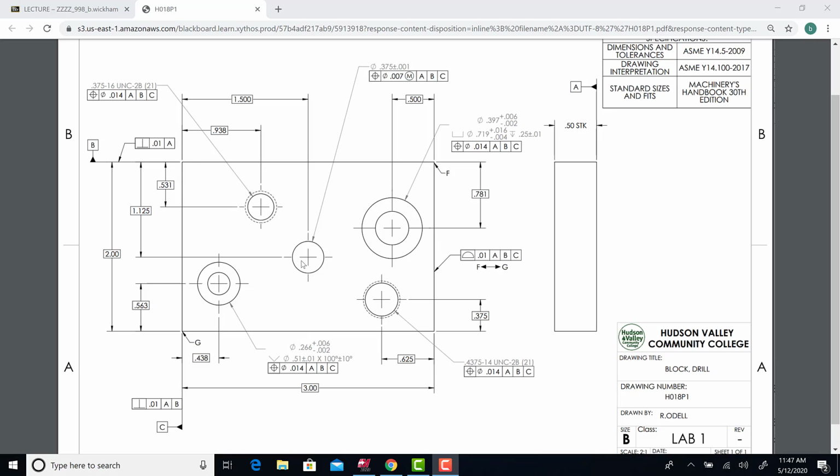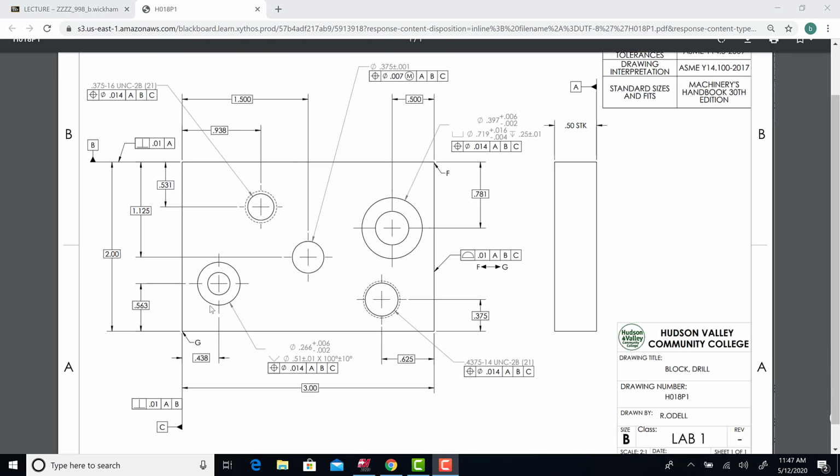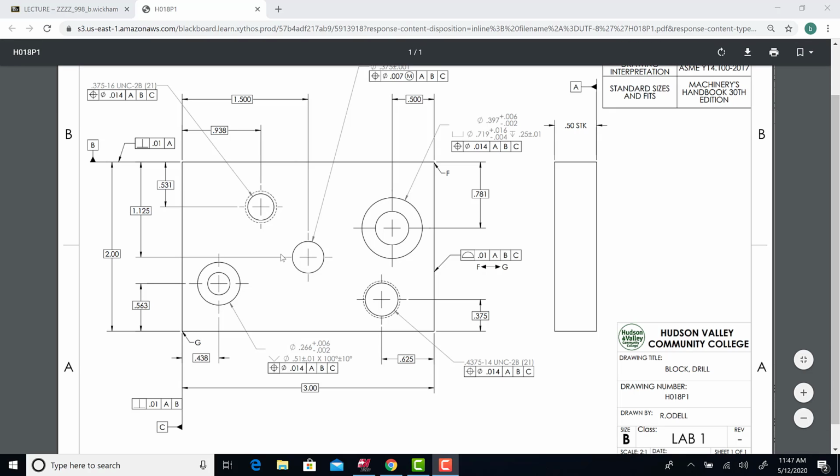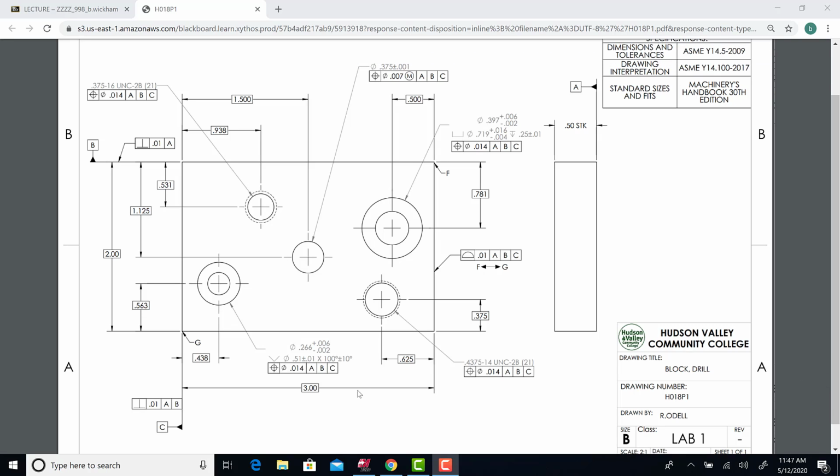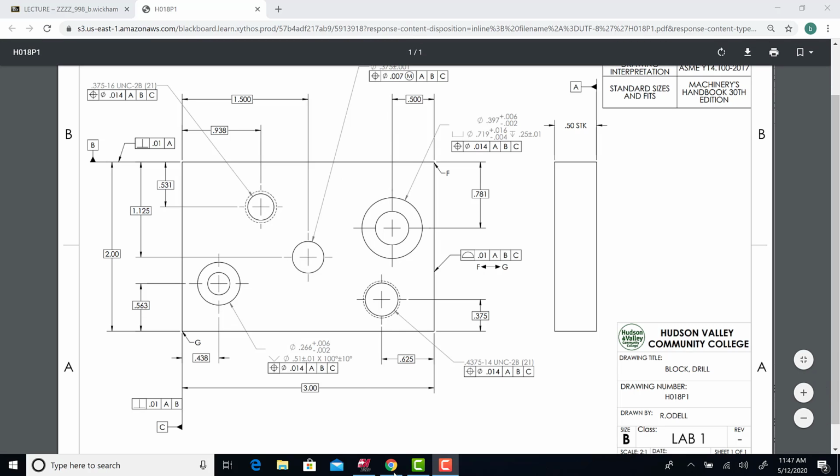The 0, 0 for this feature is the upper left. What we'll do is move the gnomon again, just for practice, to that corner. We could go from here, but we'll just move it just for practice and create a new one. Then we will use the spacebar option again and move this over instead of creating lines. We will create this on a new level, and we will actually draw the 3/8 circle.